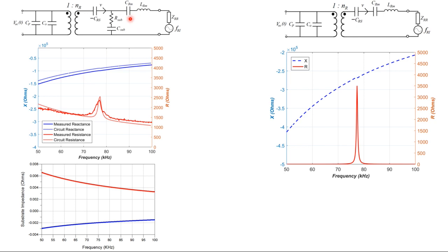It becomes non-linear, because once the CMUT collapses, you don't have a linear or well-behaving spring which obeys Hooke's law, right? Some part is collapsed and some part is still hanging from the parts where it is bonded. That creates a nonlinear compliance, which is a function of the membrane profile.